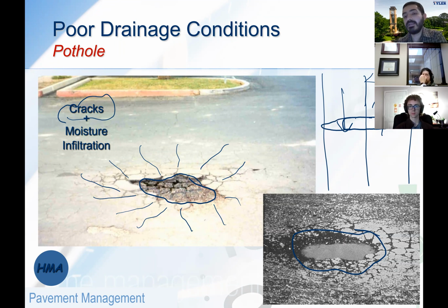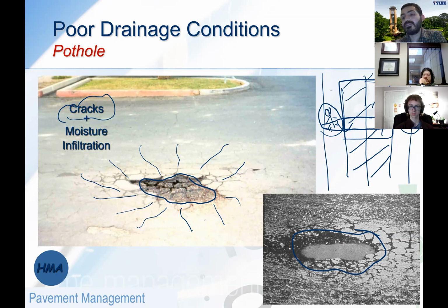Sometimes you see some of the operators sit here just to make sure there is enough asphalt being spread all the way to the edges, but the amount of weight being applied on the edges is not even close to the amount of weight being applied in the middle part of these lanes. And this is just paving, let alone compaction.